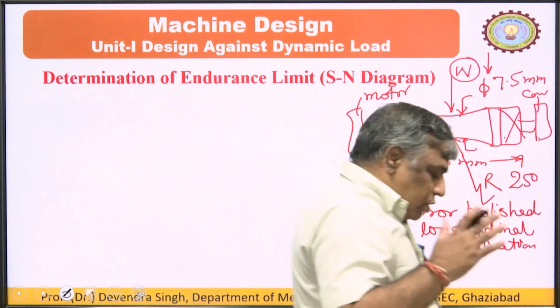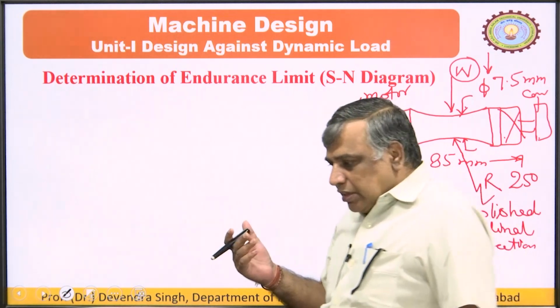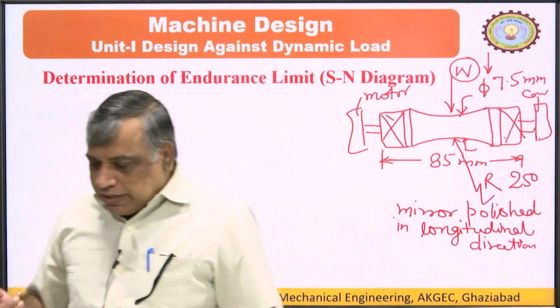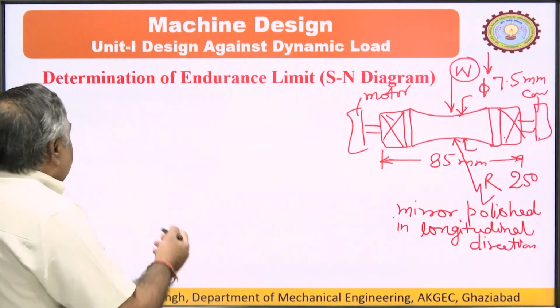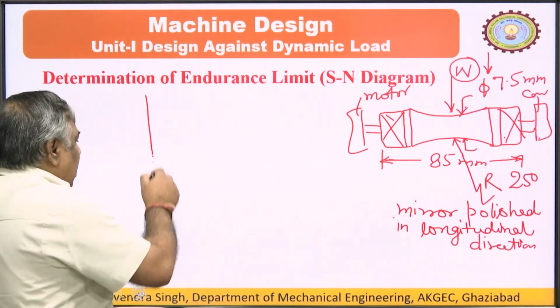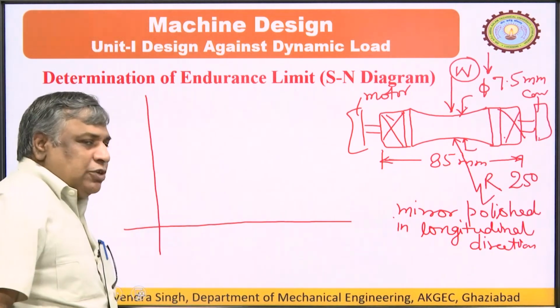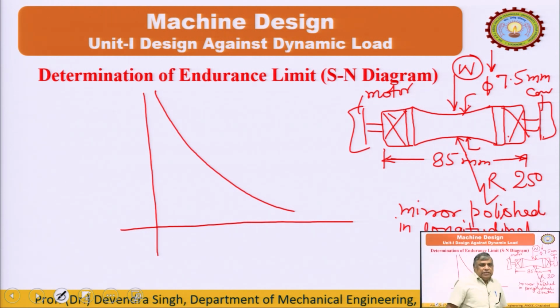Even we use the relationship between the endurance limit and the ultimate tensile strength to determine the endurance limit of any material. So, now we start to discuss the SN diagram. If we plot the data on a simple curve, even for ferrous materials, we do not get the knee point, and this does not serve our purpose. But if the same experimental points we plot on the log-log curve, then we get a knee point, and that defines the endurance limit.